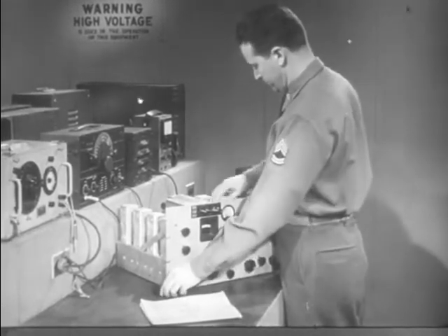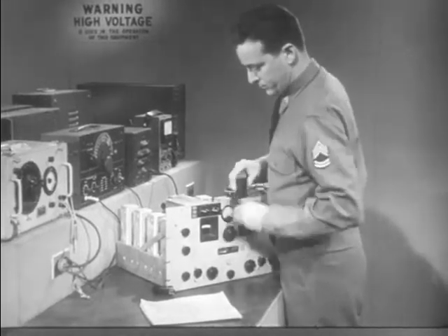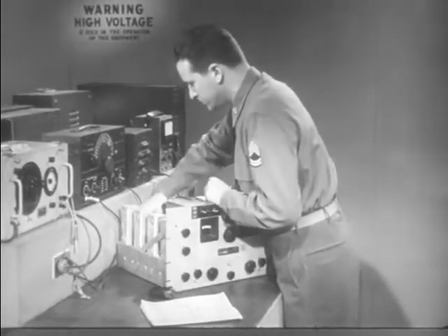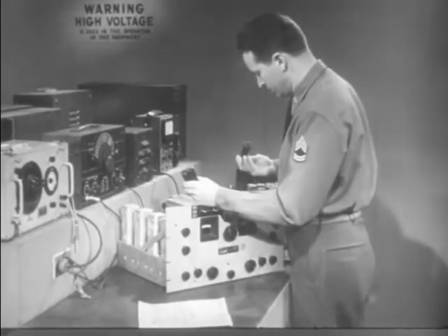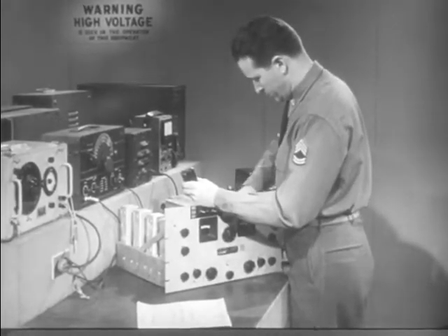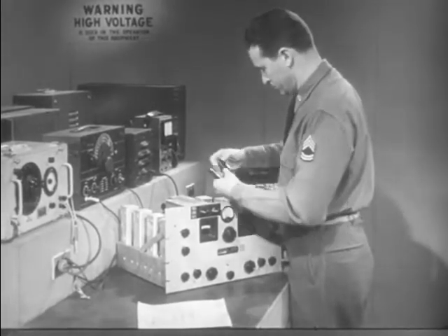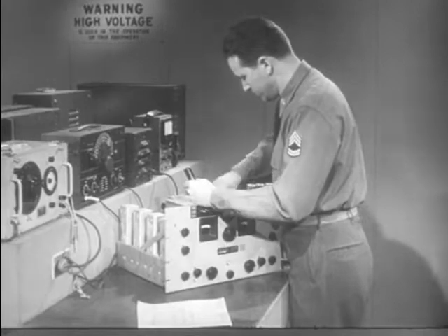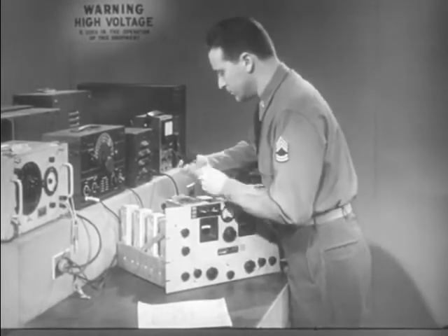Now returning to the radio receiver, before it can be aligned, it must be checked thoroughly to eliminate all other defects. Tubes are checked, voltage tests made, and a careful visual inspection accomplished. Aligning a set that has other defects only means repeating the whole process again, since change in the constants of the set, such as a new tube or capacitor, affects the alignment.